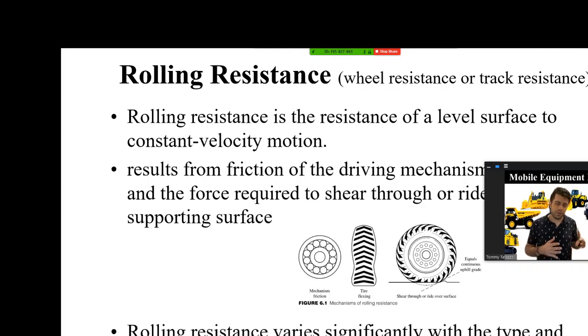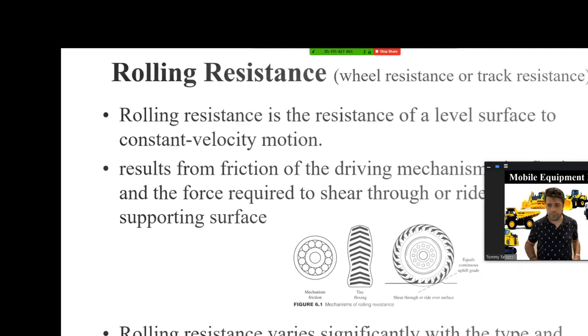If you remember, we talked about what rolling resistance depends on. We listed some factors that could lower or increase the rolling resistance. And we said that the more stable the surface of the road is, which is achievable by compacting the soil, the less rolling resistance there will be against the movement of the equipment.